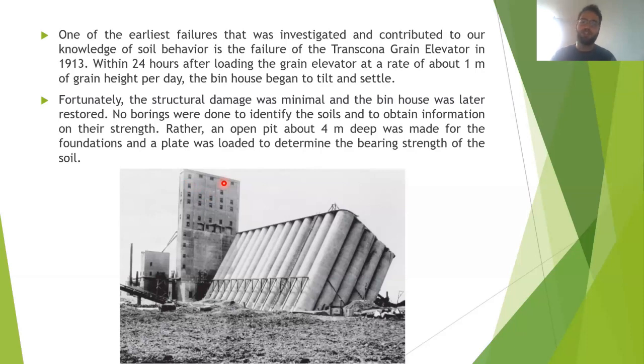That's how much soil can bear, and there's a calculation for it. We work on the calculations of how much the soil can bear for different kinds of designs. What they figured out is that the load they had there was at the limit of what the soil can take. So it basically collapsed because of the soil bearing capacity.